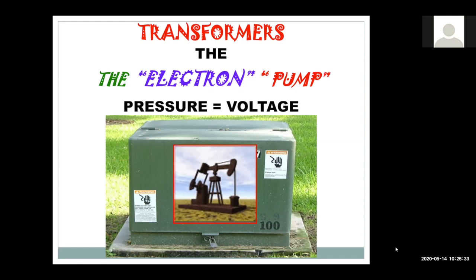And your secondary comes off of this transformer underground over to the house. It's 120, 240, single phase into the house, into the main panel, through the meter in the main panel, and is distributed to the branch circuits in the house.